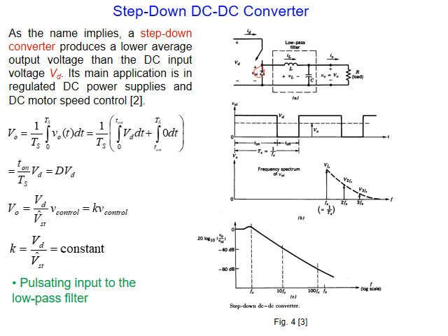This is one issue. The second issue is, you see here the voltage fluctuates between VD and 0. We need to control this. What we will do, we will put a low pass filter, an inductance to smooth the current, and a capacitor to smooth the voltage.